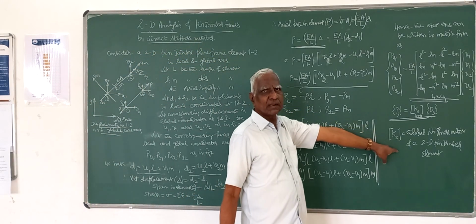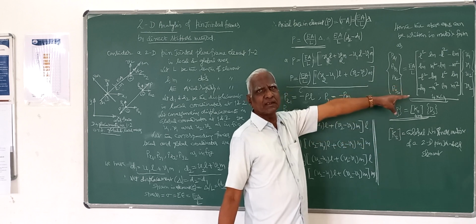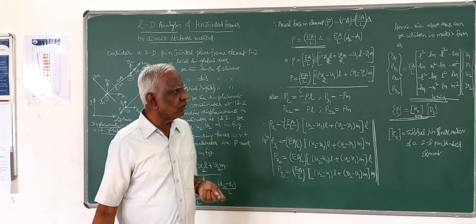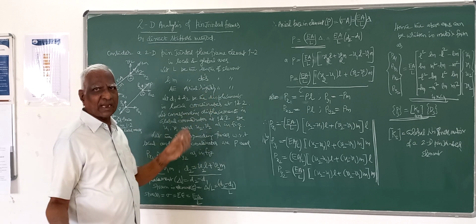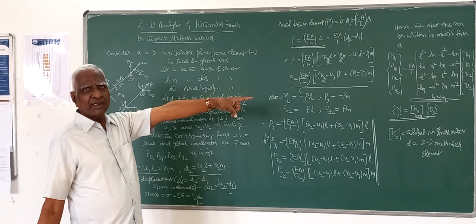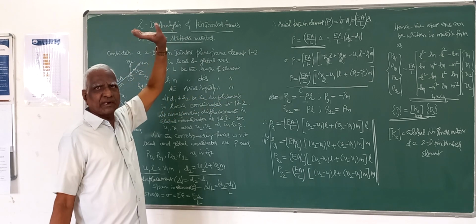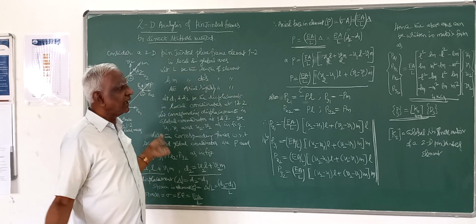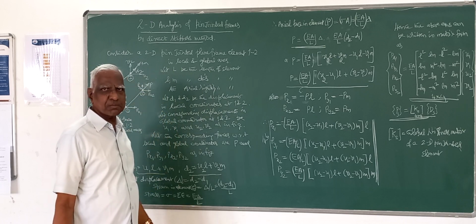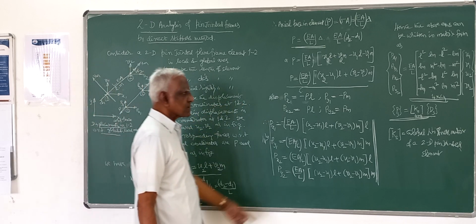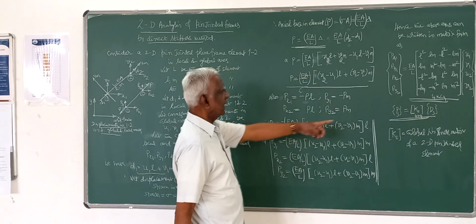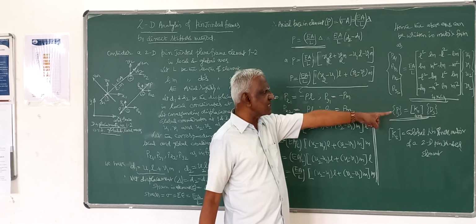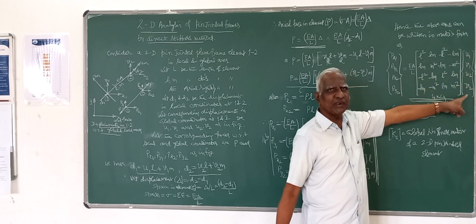Here we are generating the stiffness matrix directly in global coordinates. Straight away now we can use it. Hitherto in the other two methods, whatever you have done, you were doing the calculations. Here, already I have derived the stiffness matrix for a general pin jointed frame. Directly you can use it. Only you have to determine those geometrical properties correctly and then use simple force displacement relationship to compute the displacement. The moment you know the displacement, that is ds, that is U1, V1, U2, V2, they are all known.